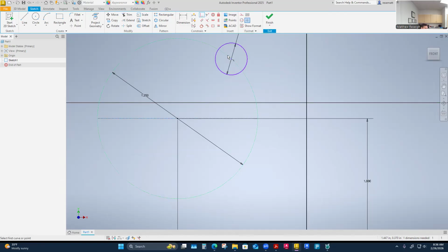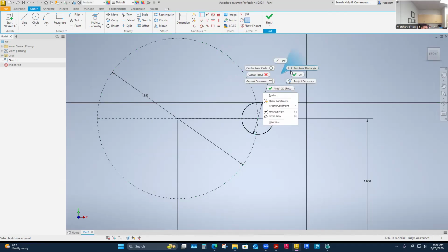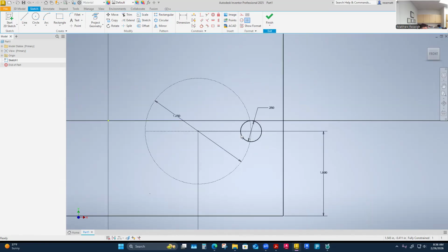But I just wanted to check because I couldn't remember if a quadrant shows up for another circle. I'm surprised it doesn't. Kind of surprising. Some grips with some selected geometry show up and others don't. So when in doubt, add some more construction lines if you need to. I'm going to pattern this thing around in the sketch, so I'll do a circular pattern.